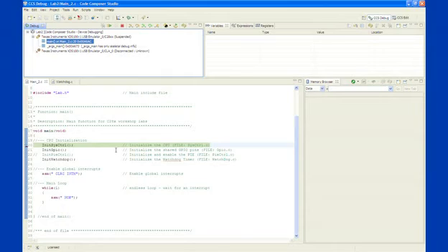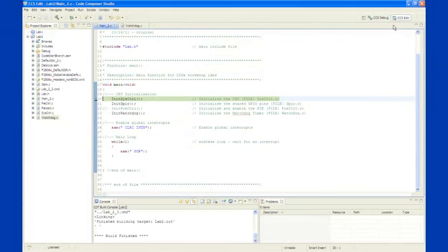So in the first part, what we've done already is we've had the watchdog disabled, and now the watchdog is being enabled. Now we're going to get to the second part, and we're going to use the watchdog to generate an interrupt. Switching back over to the CCS edit view, a couple of things I'd like you to notice is we have a couple of other files here that we've added to the project, which are called defaultisr.c and piecontrol.c and pievec.c, and we'll take a look at these shortly.